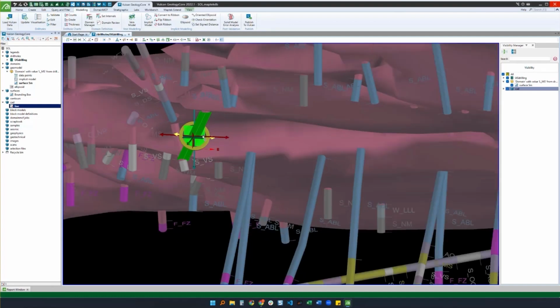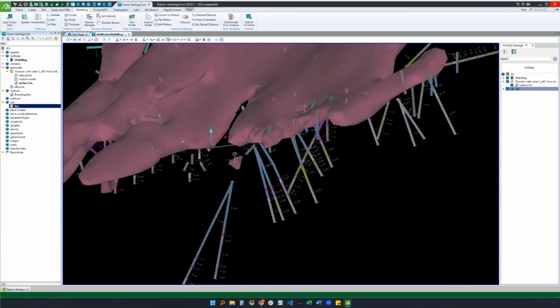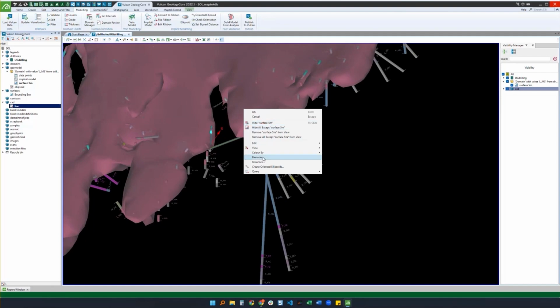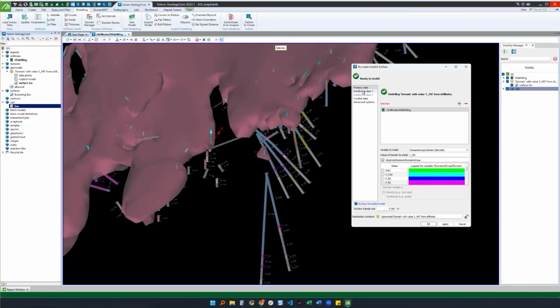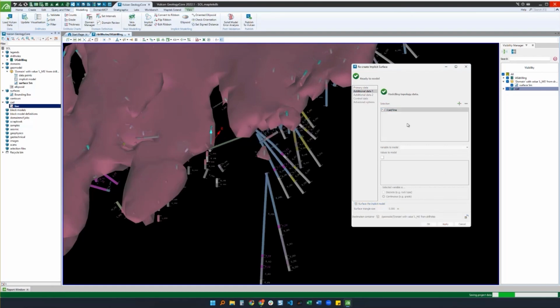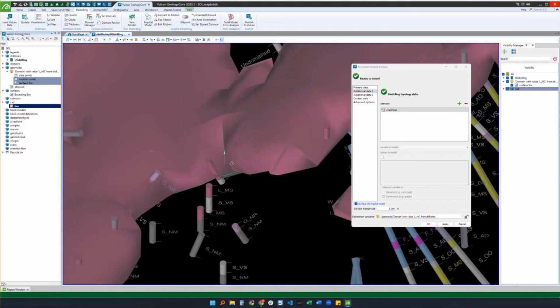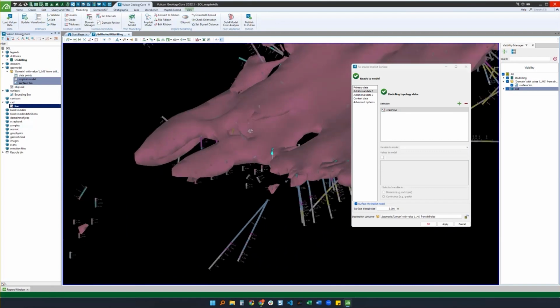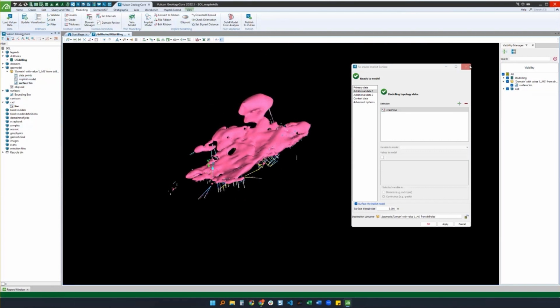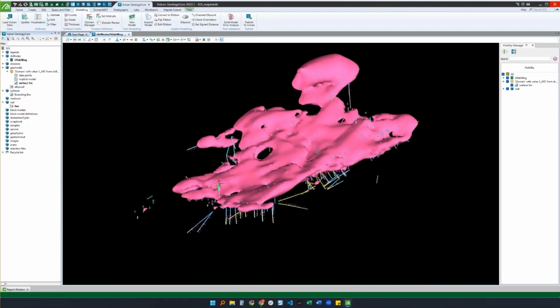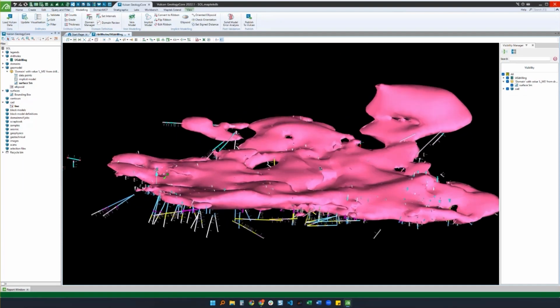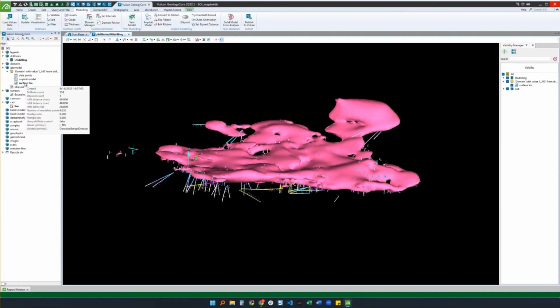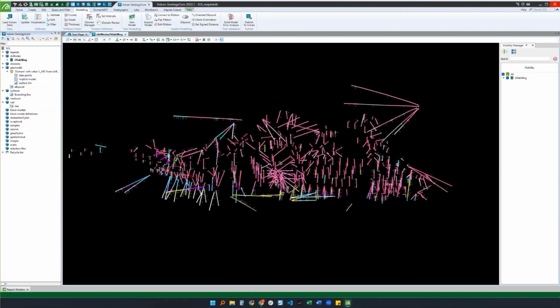Maybe something like that. And I can turn off the ribbon edit, right click on my surface, remodel it. I can go to the additional data and I can drag my ribbon in there and then I can reapply. And you can see now that's pulled the model through in that area like I would like it to. So I'm much happier with this model than I was obviously when we started. So that's good. So just as a final bit, we might want to actually, rather than modeling from